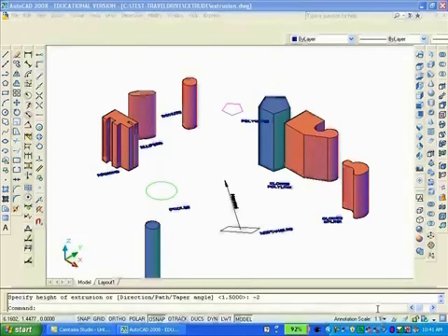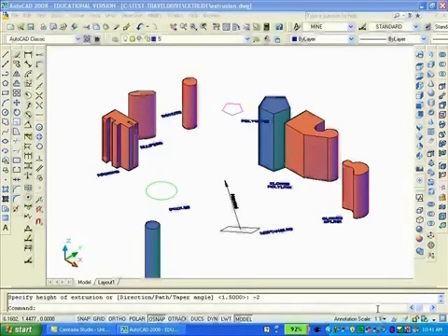Extrusion positive taper. At the top of the screen I drew a magenta colored polygon and typed 1 to specify an extrusion height of 1 unit, and 10 to specify a taper angle of 10 degrees. You can see that the taper on the object is clearly visible.